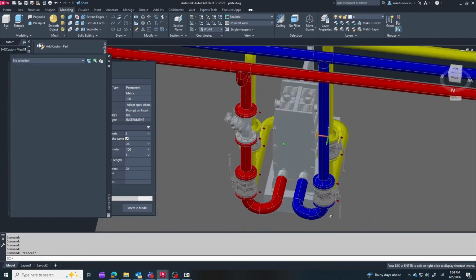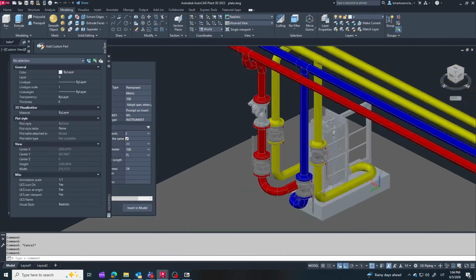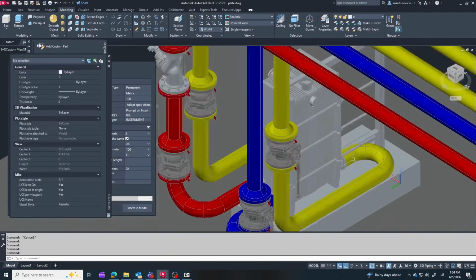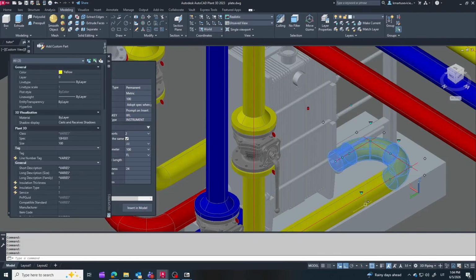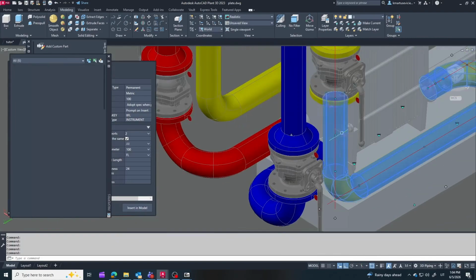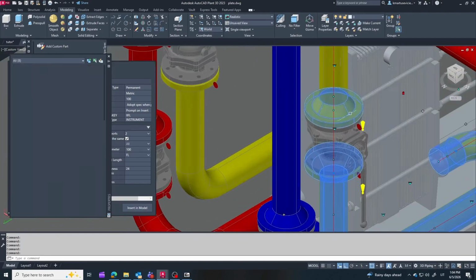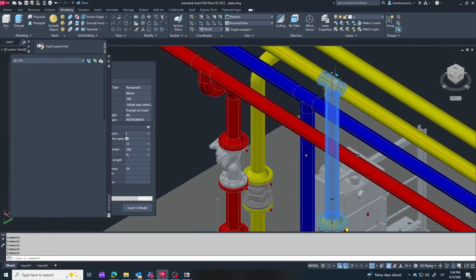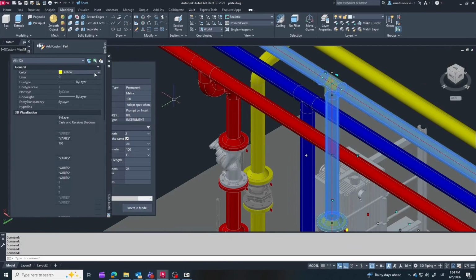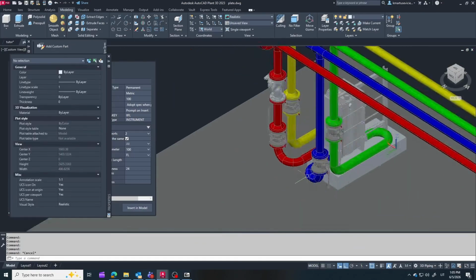In my engineering practice, I've seen situations where lines were welded to the wrong nozzles on-site. Having to cut out finished piping and redo it from scratch is an incredibly frustrating and costly mistake. Doing your color coding right in the model prevents these disasters before they ever reach the field.